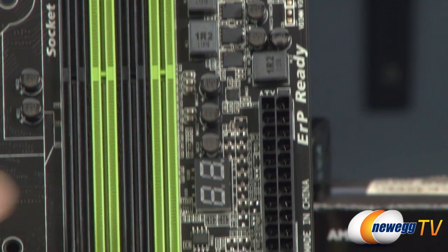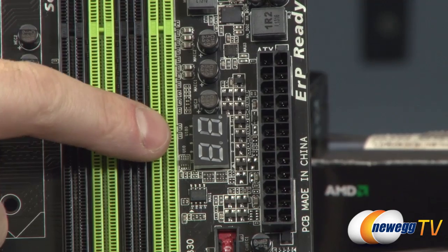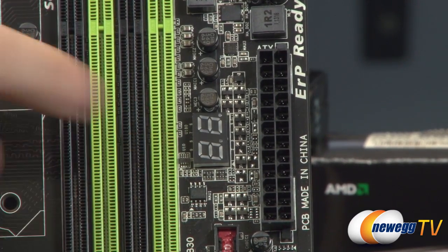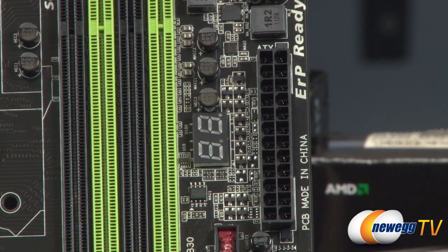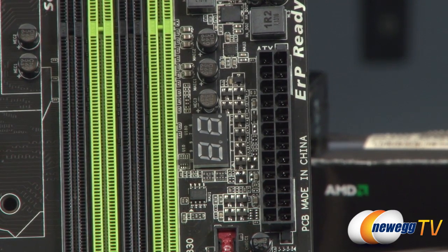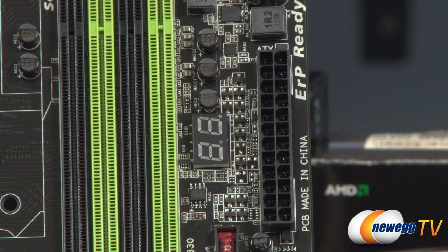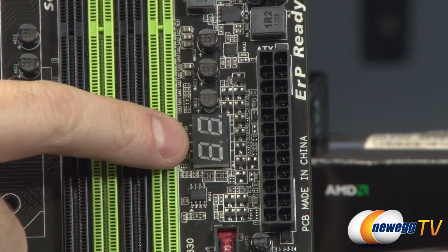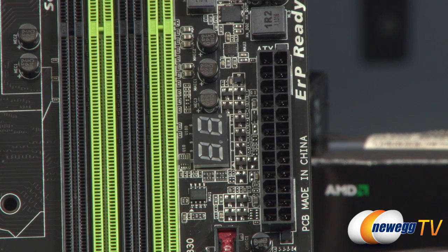Another thing this board has on it is located right here. This is what's known as a debug LED. Now, some of the hesitations people have when building their own computer are, are all the parts compatible? And if I get everything connected and I hit that power button and something is going wrong, how will I know what it is? A debug LED can be very helpful for that, because as your computer is going through POST, power-on self-test, which means it's accessing your BIOS or your UEFI, it's loading up really low-level functions. It hasn't even started loading the operating system yet.